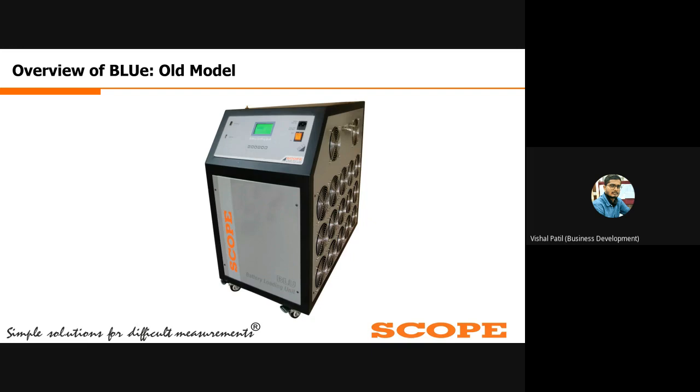In this battery loading unit, we have resistive banks, and we discharge the DC battery banks by connecting a number of resistors and making their combination automatically with the help of our intelligent processor, so that you can get the desired discharge current. For cooling the discharge resistors, which heat up due to the I square R effect during discharging, we are using forced fans.